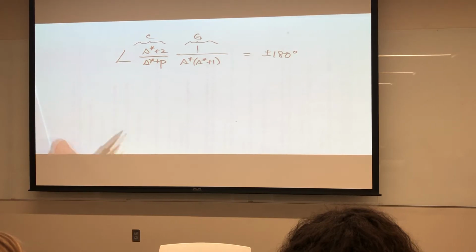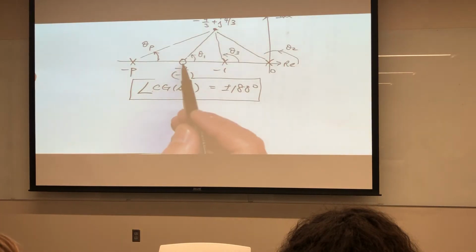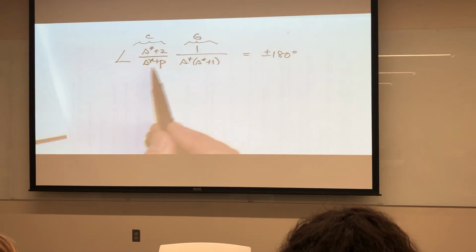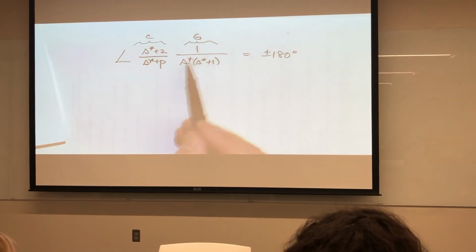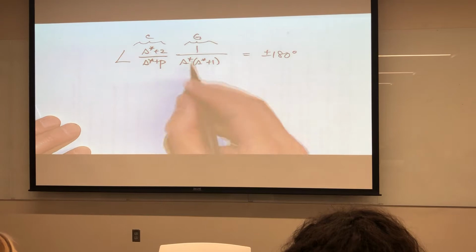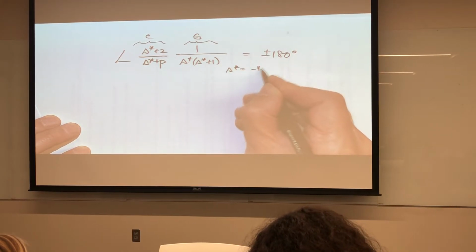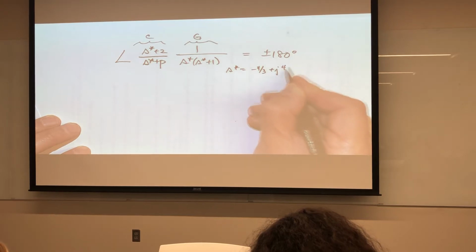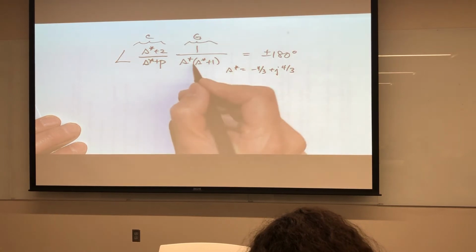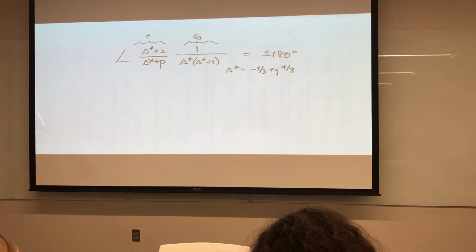So what I can do is say, well, I've got zeros and I've got poles. All these factors are known. S star is equal to negative 4 over 3 plus j 4 over 3. I should be able to enter that into my calculator, plug in all these things, and all these angles are known except for this factor.